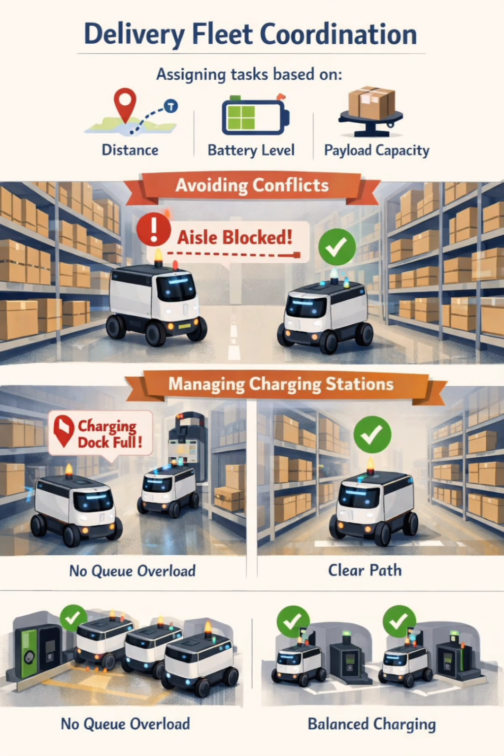Coordination is required when multiple robots or multiple subsystems must share space and resources. For example, in a fleet of delivery robots, coordination assigns each delivery request to the best robot based on distance, battery level, and payload capacity. It also prevents conflicts. Two robots shouldn't enter a narrow aisle from opposite ends in deadlock, and they shouldn't all queue at the same charging dock. Coordination manages scheduling, traffic rules, and resource reservations, so the whole system stays efficient and safe.